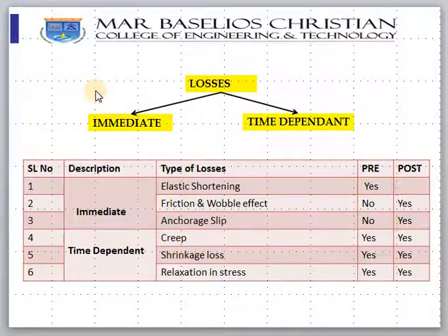So in short, what's happening is, we have seen the pre-stressing. There is an initial pre-stress in the steel. Let us say we are using tendons having stresses of 1500 to 2000 Newton per millimeter square, and once it is stressed and the concrete is cast, and when we cut the steels, we are supposed to experience the same stresses actually, but normally it doesn't happen.